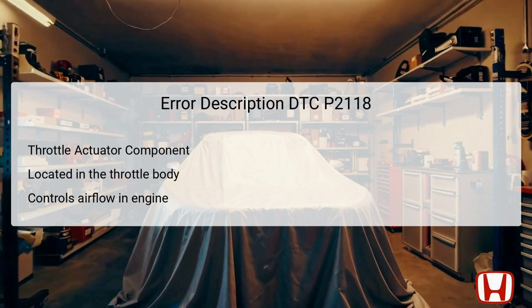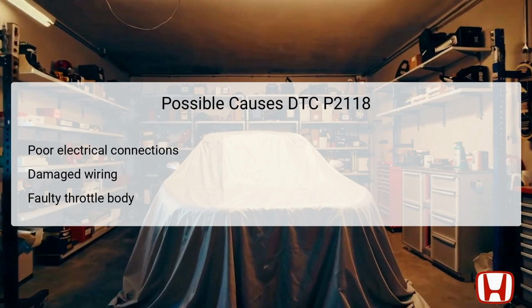This code can arise from either electrical issues, such as poor connections or damaged wires, or mechanical problems within the throttle body itself.